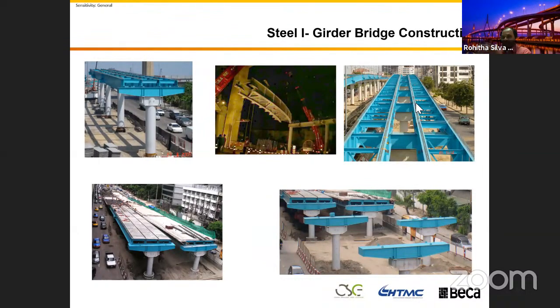The first couple of slides, what I explained to you, you can build the bridge using short spans, like 30 meter, 35 meter, 40 meter, maximum 50 meter, but not recommended. These bridges we build like 30, 35 meter. It could be a series of I girders, or it could be a series of steel girders.